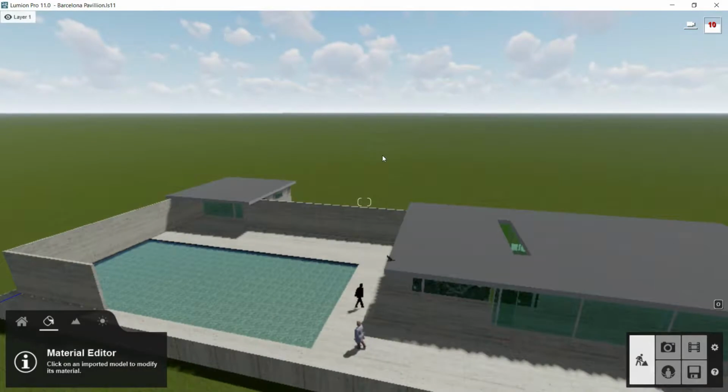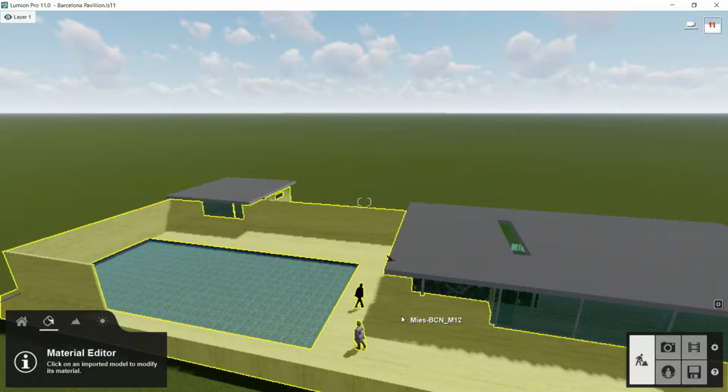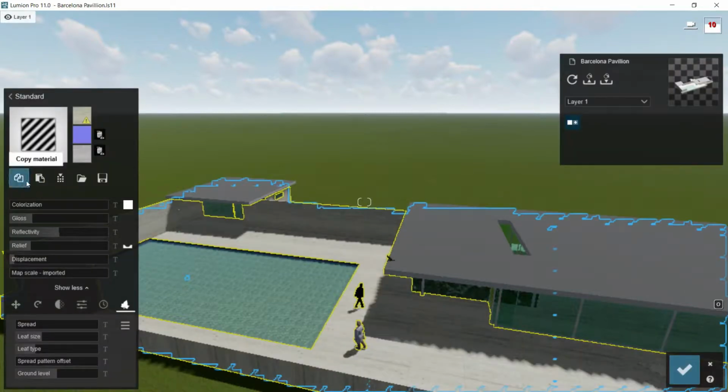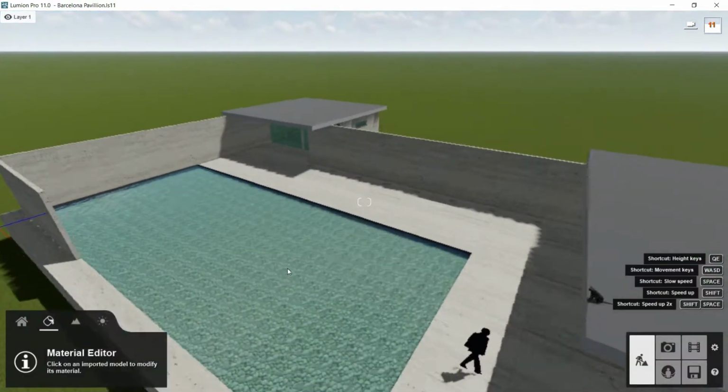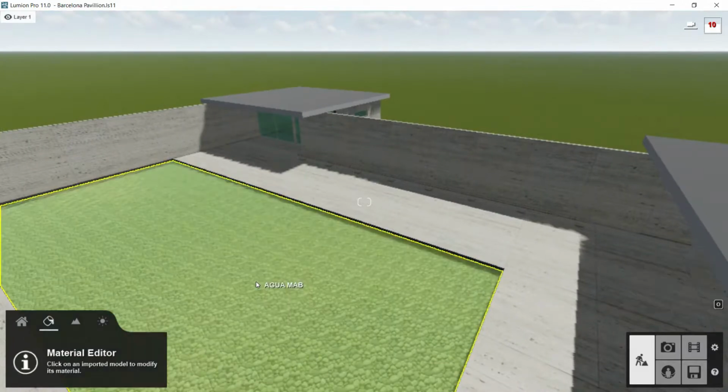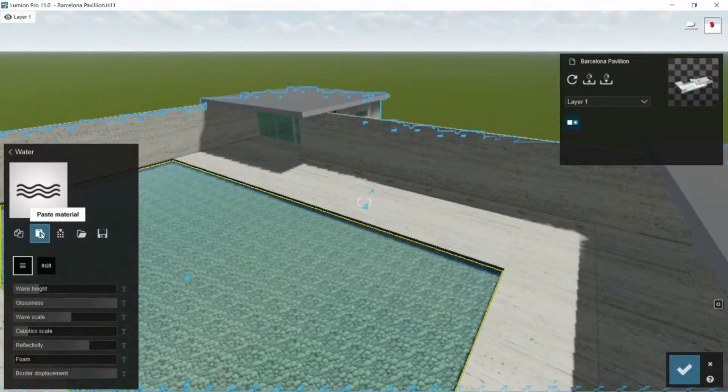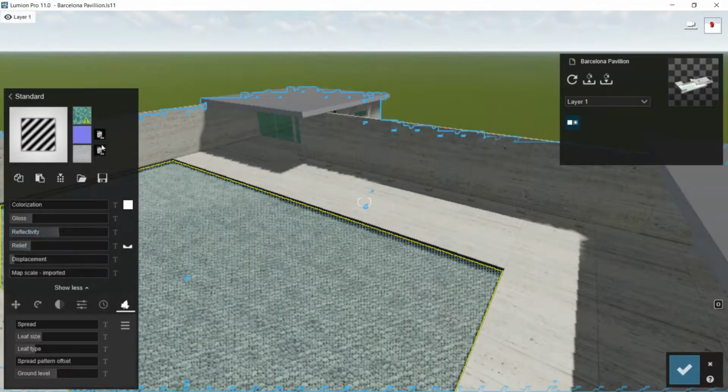Once we have created our own materials with our own presets, maybe we want to save it or copy it or whatever. So we should go here again, and now it's time for checking these options. I'm copying right now this stone with all these presets, and then I will click here, Save Changes, and for this example I will go here to this swimming pool, and I will click on this material, and I will say Paste, and then all the characteristics, all the presets have been pasted here on the swimming pool.